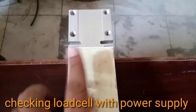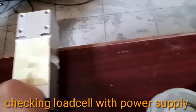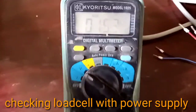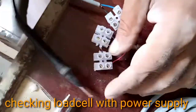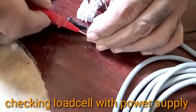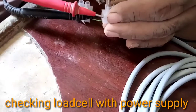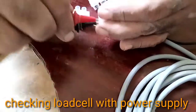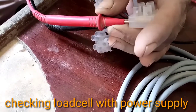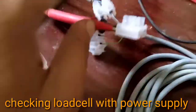Now we can apply the load, fix it with hand, and apply load at the other corner and check the output millivolt. First of all, we connect our meter cables with the connector properly. You can see here our friend connects and checks the load cell with a multimeter. How you can check it with a multimeter and apply load.